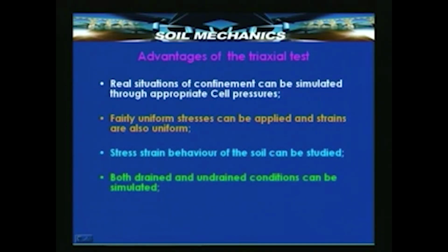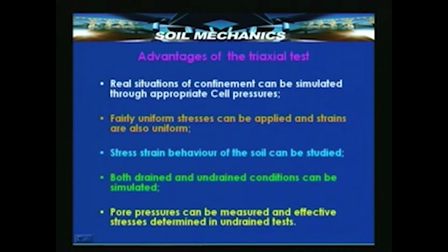Lastly, both drained and undrained conditions can be easily simulated in a triaxial test. In the direct shear test, on the other hand, we found that undrained conditions can hardly be simulated adequately, right. Then finally, pore pressures can be measured and effective stresses can be determined during the undrained test.